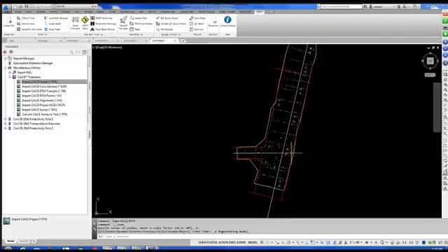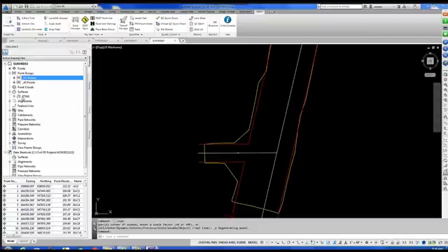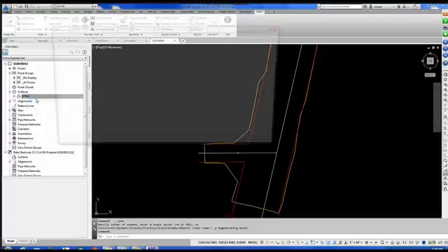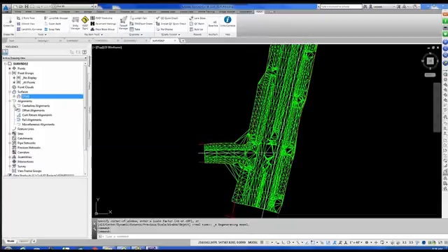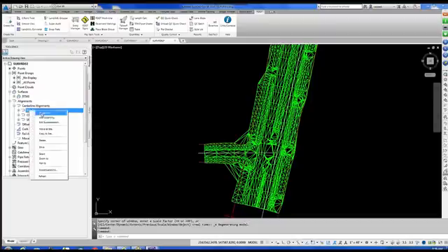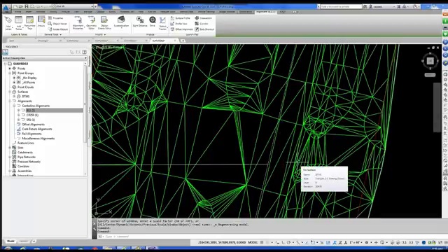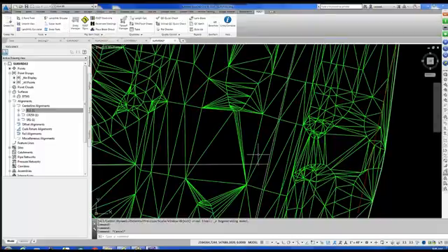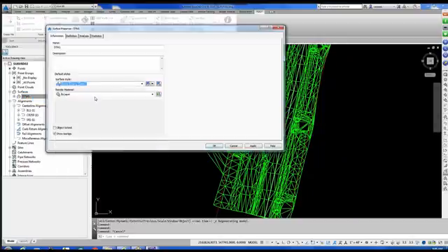All right. Do a zoom extents. We zoom in, and there's our surface. So now what we have in here now is we now have a point group called all points. Okay, let me go ahead and update this one here. We have a surface called DTM. What we're going to do is we're going to select it and right-click, and we're going to change the style of that to triangles existing green, so you can see the surface. Okay, and then we have 3 centerline alignments. We have our baseline 1, we have star 1, and we have County Road 259. So I'm going to pick on baseline 1 and say select, and you'll see that, see how it's highlighted? So there's your alignment. So what it's done, as we said right off the bat, is it creates valid Civil 3D entities from that import from the CAiCE tools. Okay. Now, I'm going to go ahead and change my surface style back to simply a border existing green.